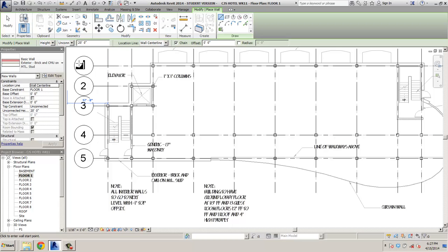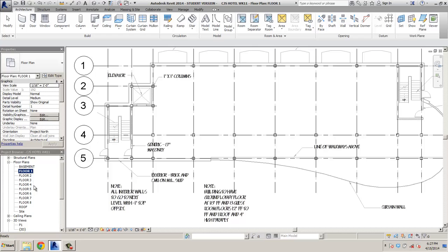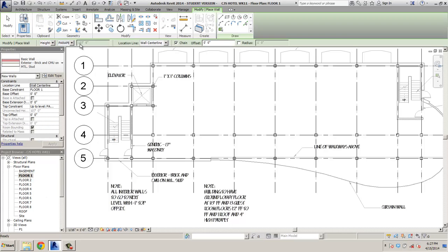In the options bar at the top, this is our options bar, we're going to set our height to parapet. We've already set our elevations in here. Actually, we didn't do that, did we? We did that last week. We set all the elevations. Let's just go check and make sure everything is... I know they're in there because we've got all our floors in, so...